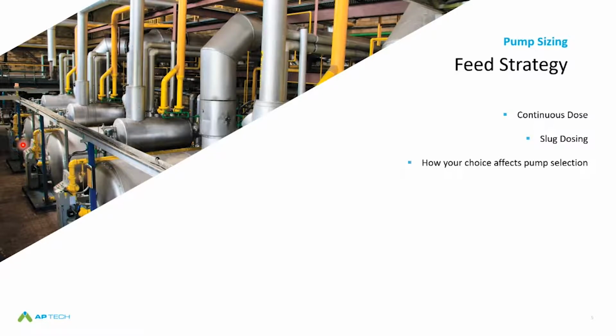That chemical controller is going to register that pulse, and it's going to dose an appropriate amount of product for that specific volume of makeup water that was brought into that system. Whether that's a boiler or a cooling system or even a closed loop system, what's the mass balance? What is required for that 10 gallons or that 100 gallons to treat that volume, specifically how much or how long that chemical pump needs to stay on for.